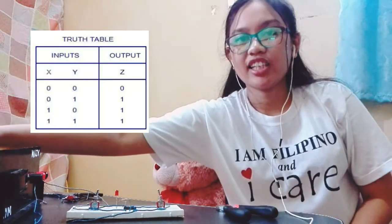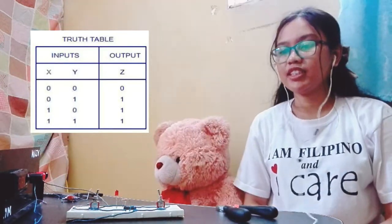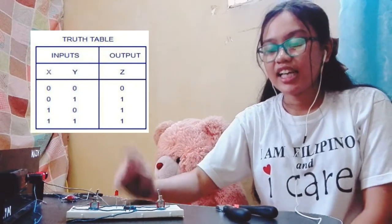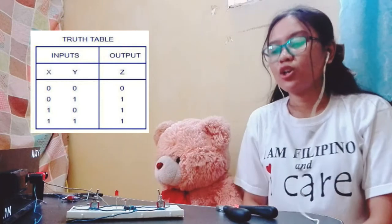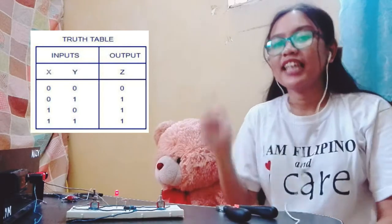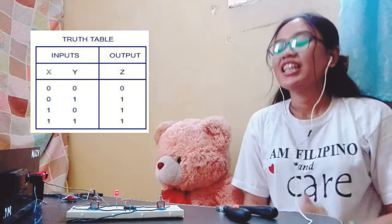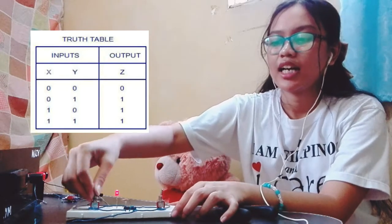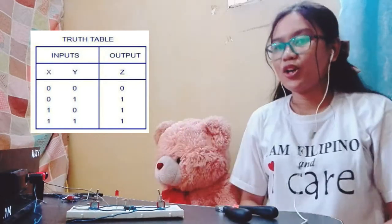Now let us test our circuit. First, let us turn on our power supply for the 5 volts VCC. Here we have our circuit. The LED doesn't have any light since both of the switches are in low input. But if any of the switches are in high input, the LED will turn on. And if both of the switches are in high input, the LED will still turn on. And the LED will only turn off if both of the switches are in low input.